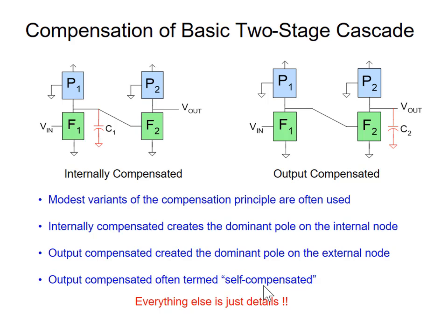Now when I add these capacitors on, what am I going to do to the bandwidth? Going to be reducing it. If that capacitor is very big, I might dramatically reduce the bandwidth. I might dramatically reduce the gain bandwidth product. And if I've got 2 poles that are widely separated, I'm making the amplifier look about like a first order system.